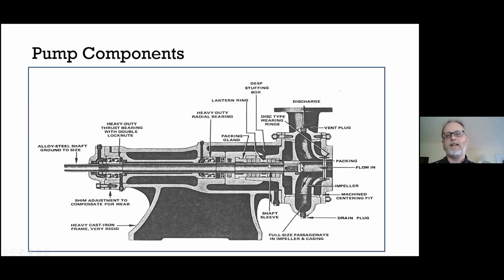So the packing gland prevents leakage from the pump, but it also prevents air from getting in, because it seals both air movement across the shaft and water movement. And then we've got, you can see here, the bearing that supports the shaft. Going back, here's the other set of bearings supporting the shaft all the way through, and then we tie on the impeller at this point here with the follower lock nut here. So that's the cutaway.